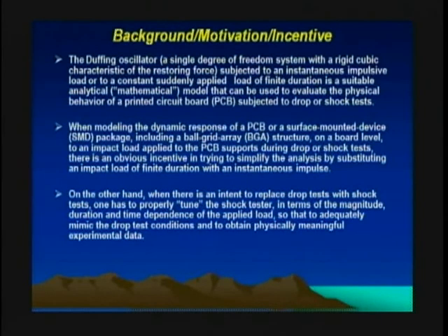We have already done that because we derived this equation and it turned out to be of the Duffing type. When modeling the dynamic response of a printed circuit board or a surface-mounted device package, including a ball grid array structure on the board level, to an impact load applied to the PCB supports during drop or shock tests, there is an obvious incentive in trying to simplify the analysis by substituting the impact load of finite duration with an instantaneous impulse. On the other hand, when there is an intent to replace drop tests with shock tests, one has to properly tune the shock tester in terms of the magnitude, duration, and time dependence of the applied load so as to adequately mimic the drop test conditions and to obtain physically meaningful experimental data.